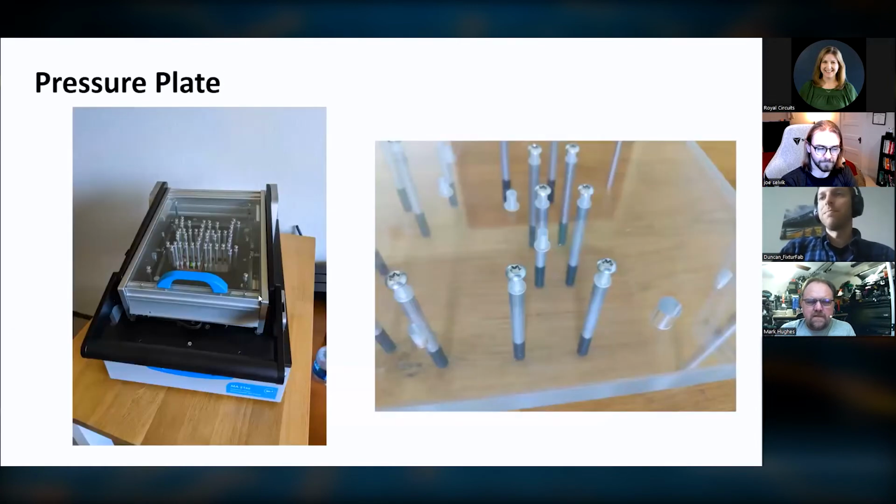Yeah, those pogo pins, they've got forces in the range of what, like 1 to 5 newtons? Yeah, so you can get ones that are half a newton, but we typically use 1 to 1.5 newton probes, and you can get stronger ones as well. By themselves it's not that much force, but if you have 600 or 1,000 test points on your circuit board, it adds up quickly. Yeah, that would be insane. So 600 newtons, 60 kilograms, that's like the weight of half of me on your board.